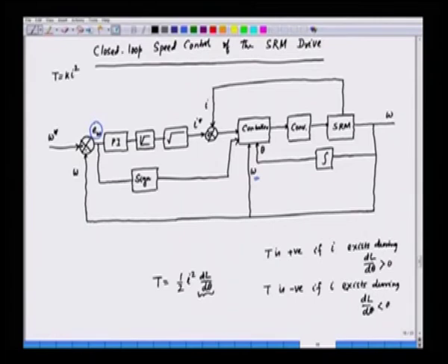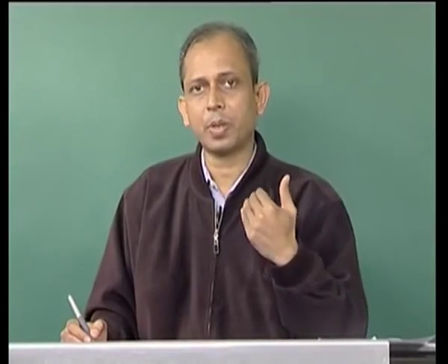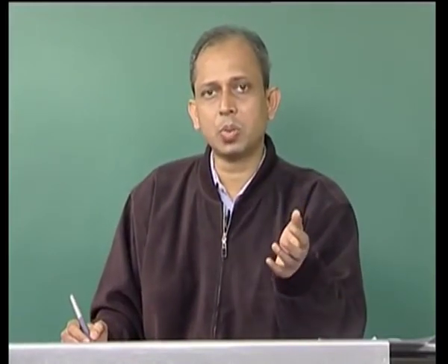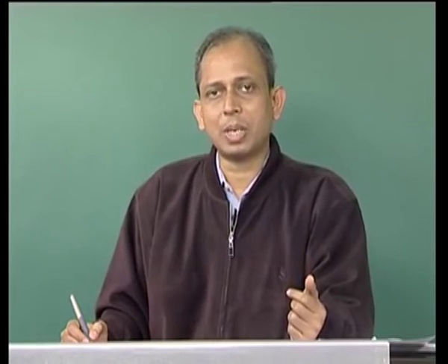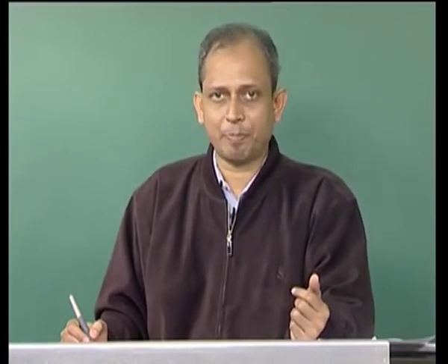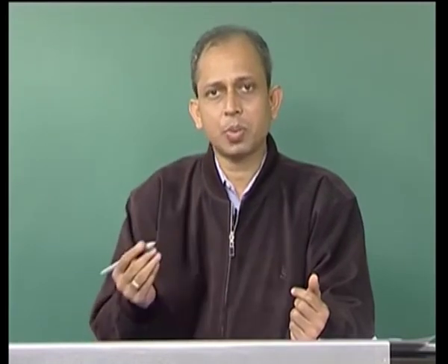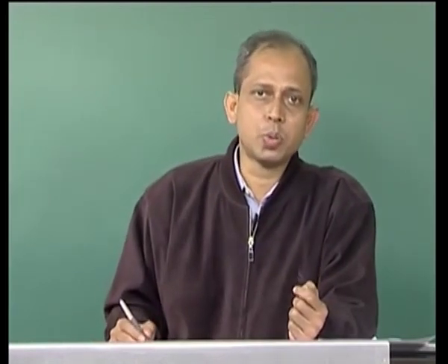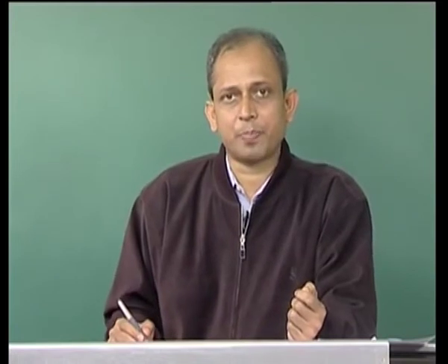So we can have the proper switching so that we can make the torque positive by switching the current in positive dL by d theta, or if you want the torque to be negative for deceleration or for braking or for speed reversal, we need to have negative torque, and that can be ensured by switching the current during negative dL by d theta. Now let us try to see the various topologies used for converters.